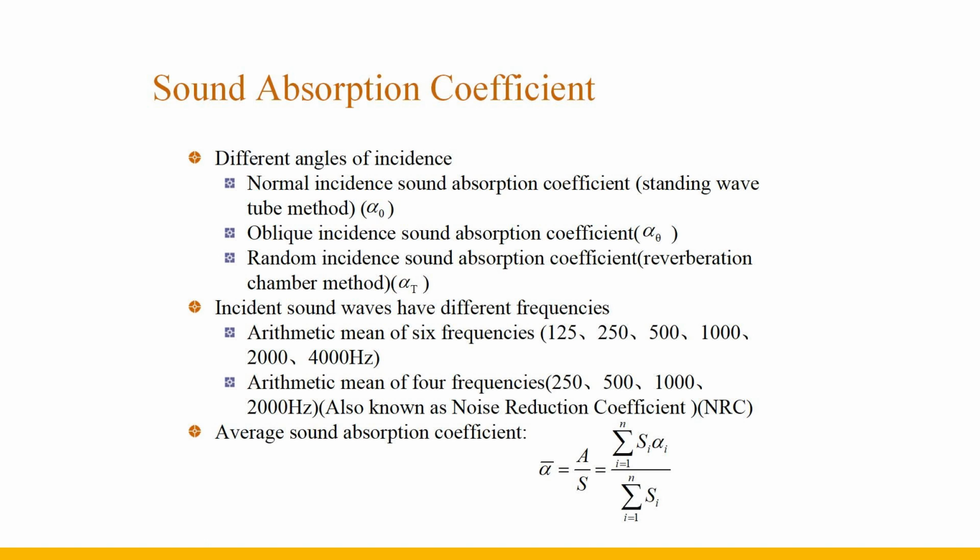Sound-absorbing materials can be roughly divided into 5 categories according to the appearance and structural characteristics of the material. Porous materials are suitable for absorbing medium and high frequencies. Plate-like materials are suitable for absorbing low frequencies. Membrane material is suitable for absorbing low and medium frequencies. Perforated plates and flexible materials are suitable for absorbing medium frequencies. These materials can be used alone or in combination.